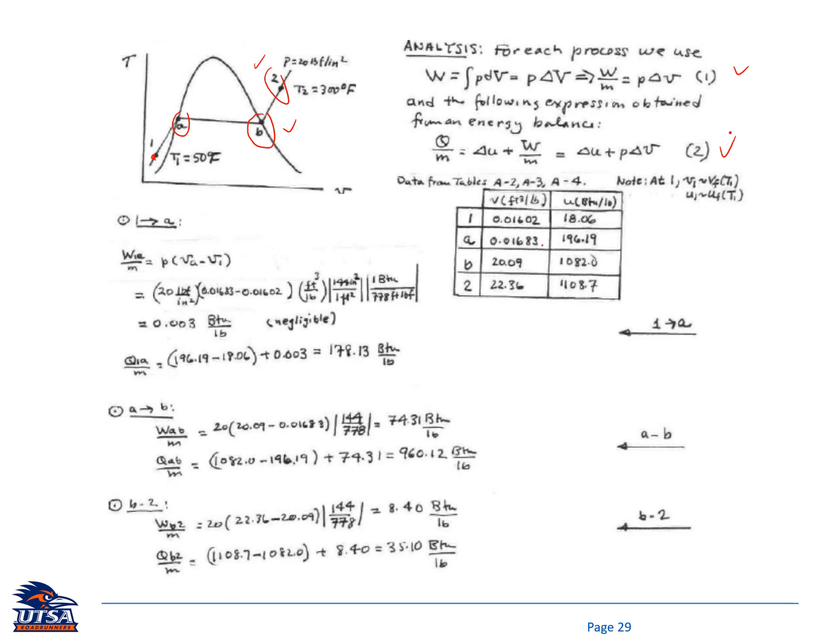So what you need to do there is you use different tables to get the thermodynamic properties. Use table A2 for the saturated state with a given temperature, and then use table A3, the same thing but for a given pressure, and A4 to get the data at state number 2.